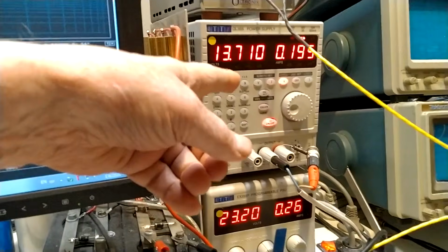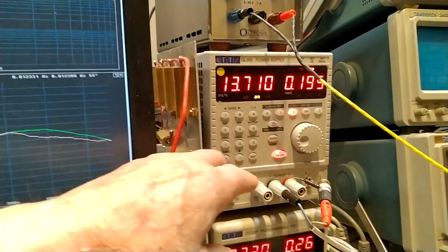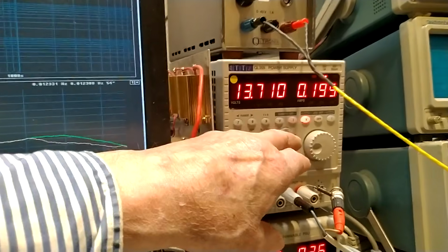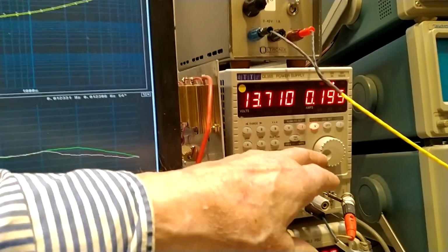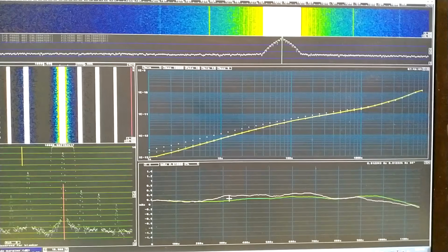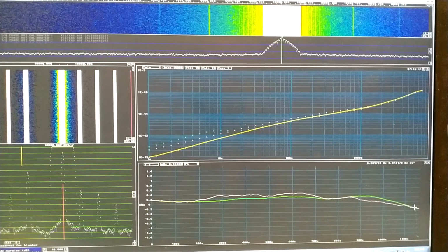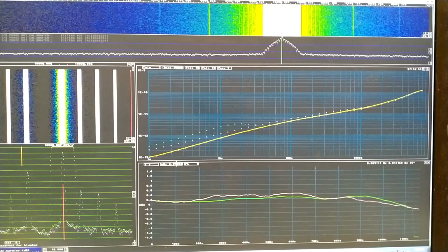measurements. This is the power supply for the Wenzel oscillator. I change it by 1 step, that is 10 millivolts, like that. The Wenzel oscillator is connected through a 5 ohm resistor and a very big capacitor. I don't remember exactly, but something like 1 farad. You can see now the frequency has changed dramatically. The green trace is now coming out of scale, so I change the scale by a factor of 10